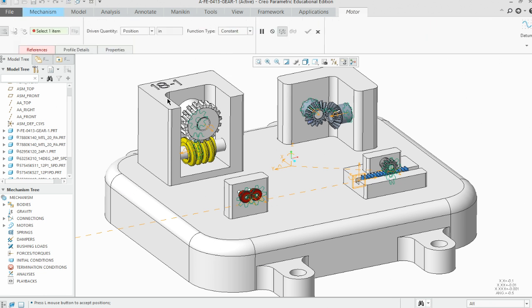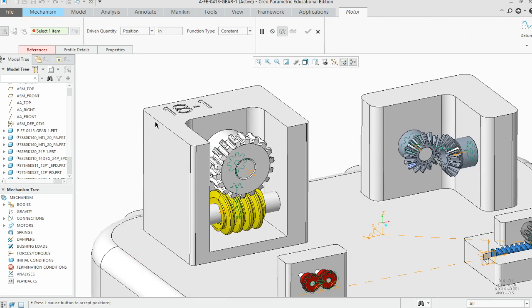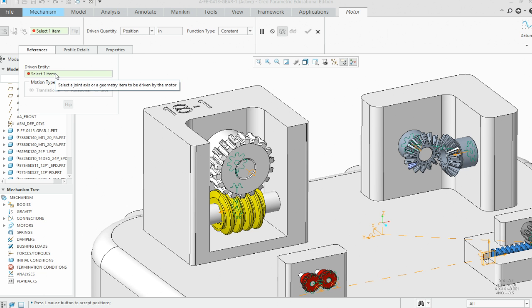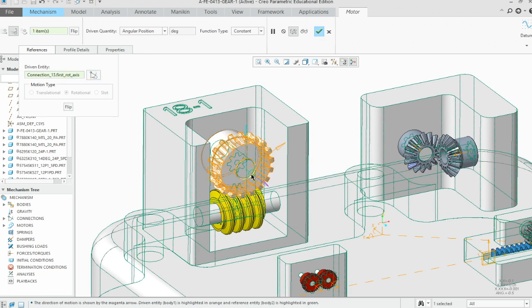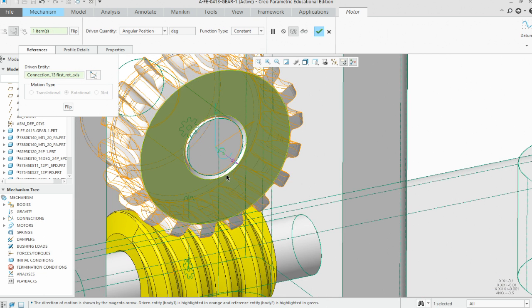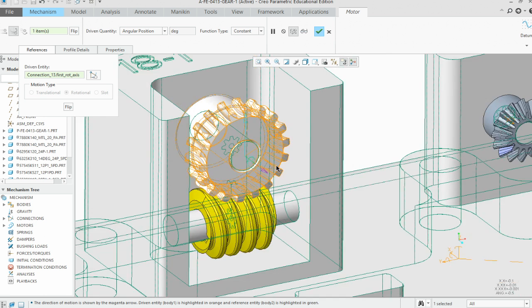That servo motor is the one that we wish to put into place. It's first asking for the drive entity that we want to do, and you're kind of going, what is that? Where is it? That right there is that little orange swirl that we used before to place the gear. Once we've got that into location, you can just grab it. You also get to see a little swirl like a tornado. That tornado is telling you what direction that object is moving.